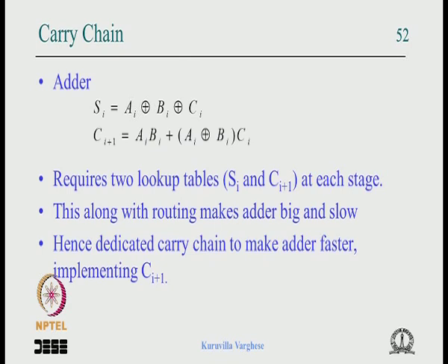So let us look at this issue now. Maybe I will introduce that. There is a carry chain within the FPGA slice. Now you know the equation of an adder. The sum for any particular index, say Si, is Ai exclusive-OR Bi exclusive-OR Ci.